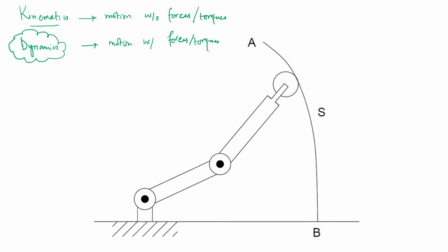Now, in addition to that, just consider that in this particular case, if you have length A1, this is going to have a point where this whole mass is centered, and that is going to be heading downwards. And similarly for length A2, you have the mass of this link going downwards as well. So this may be like M1G, and this is going to be M2G. And then because these links are rotating as well, this is going to generate a moment of inertia as well. So there is going to be J1 and J2, something like that.